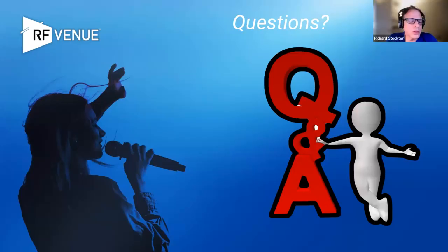Rich, do you want to add something? Yeah, so overall, yes, if you're curious about WMAS, you should do the research because it's apples to oranges. Shure is using 800 kilohertz wide carriers. Sennheiser's doing 6 megahertz in the US, and 8 megahertz in Europe. But both of it is basically multiplexing. It's combining sub carriers within one big carrier.